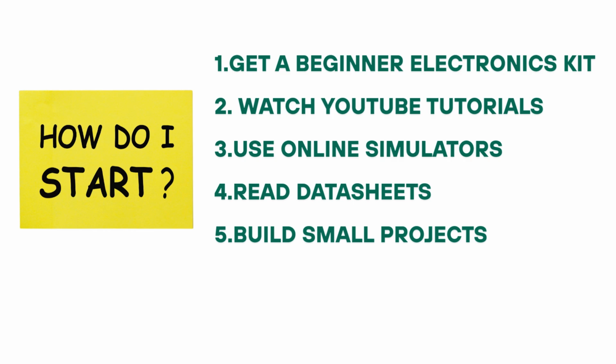Use online simulators like Tinkercad or Proteus to build circuits virtually. Read datasheets to understand how each component works. Build small projects like blinking LEDs, light decorators, buzzers, or fan controllers. You don't need expensive tools to begin, just curiosity and the willingness to try.